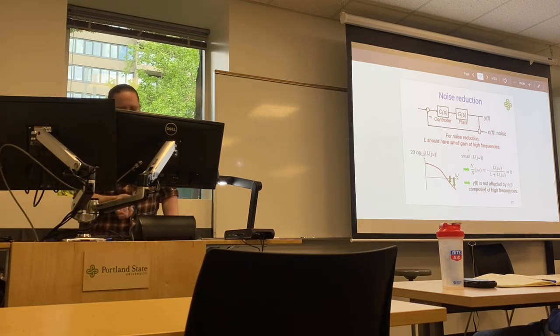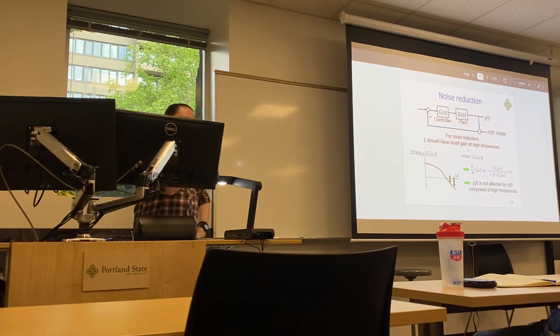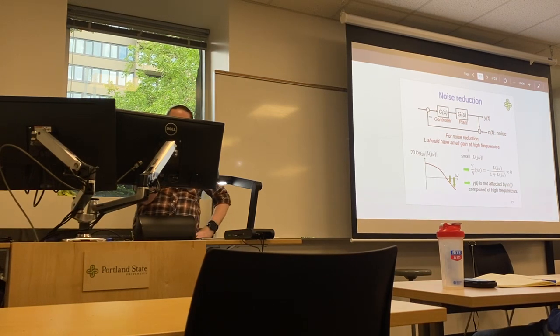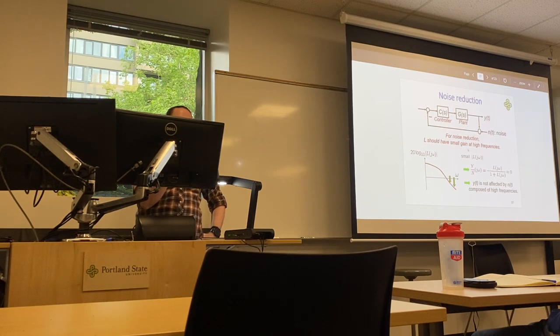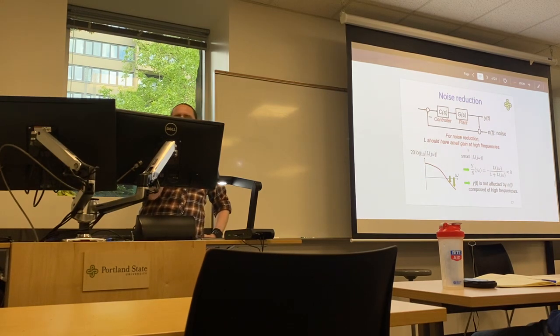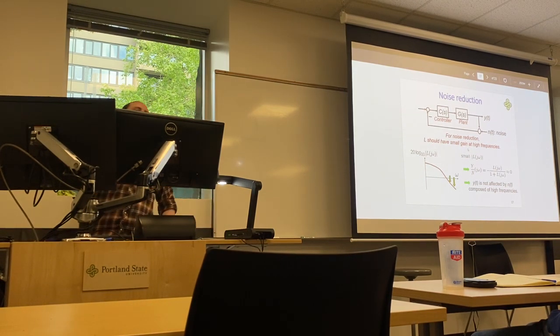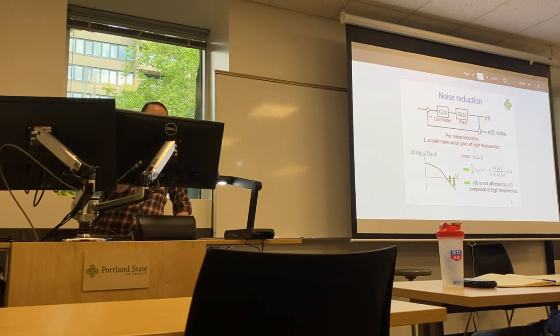That also factors in for how long we want to have that phase boost that we put in with our design. If we decrease that phase boost, frequency Z and frequency P, we would end up with lower phase boost, depending on what we're designing for, but we would reduce some more of the noise because we would have less of that gain bump that occurs in the phase boost area.